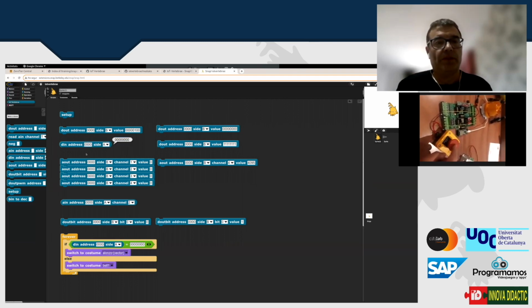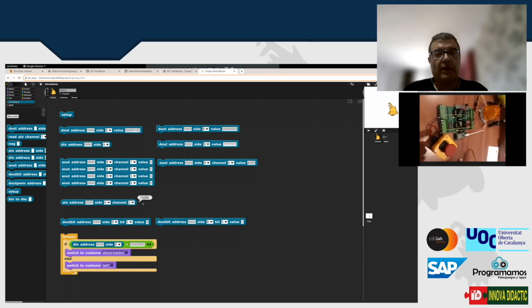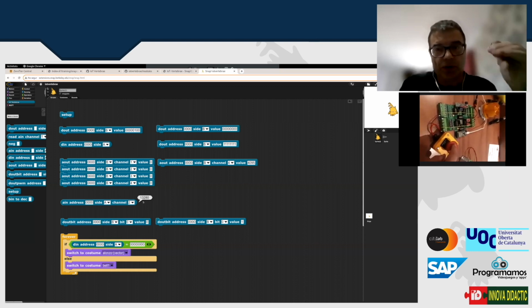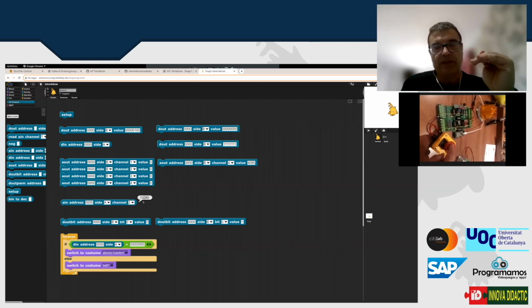Now we're about to click on all the 4 analog outputs. I am writing 0, and now I am about to read this value, and I see that the value is 13,000 more or less. This is because minus 10 volts is just a 0 number, and just in the middle there is like 26,000 plus 10 volts. Then when we are sending 0, we are reading this value.